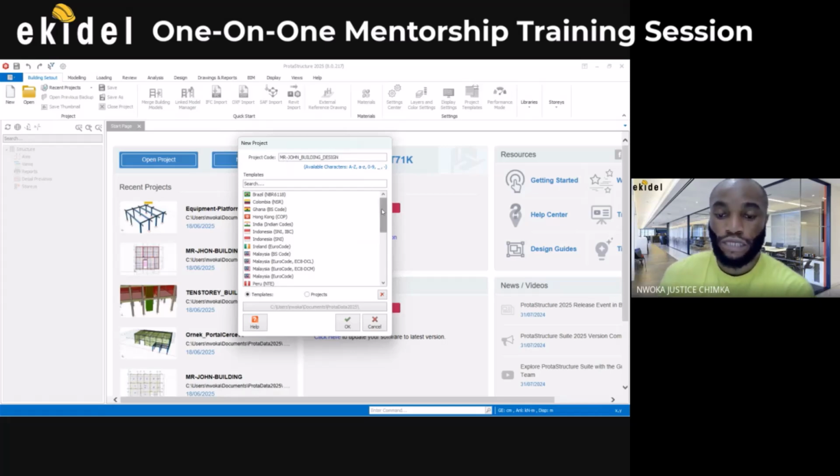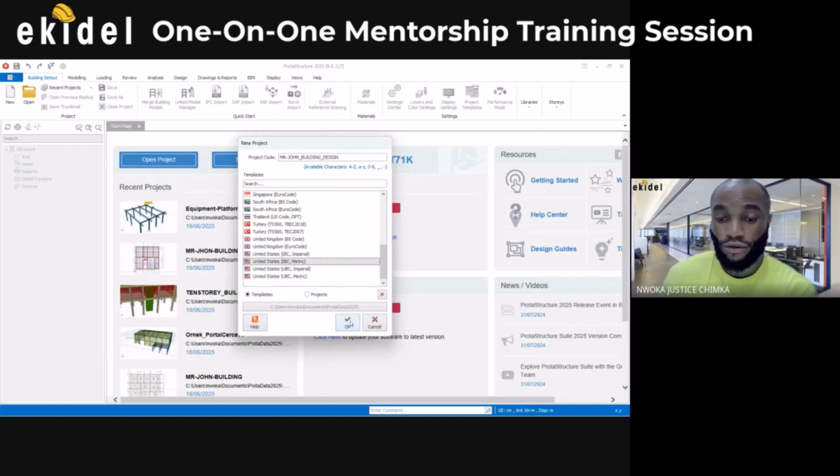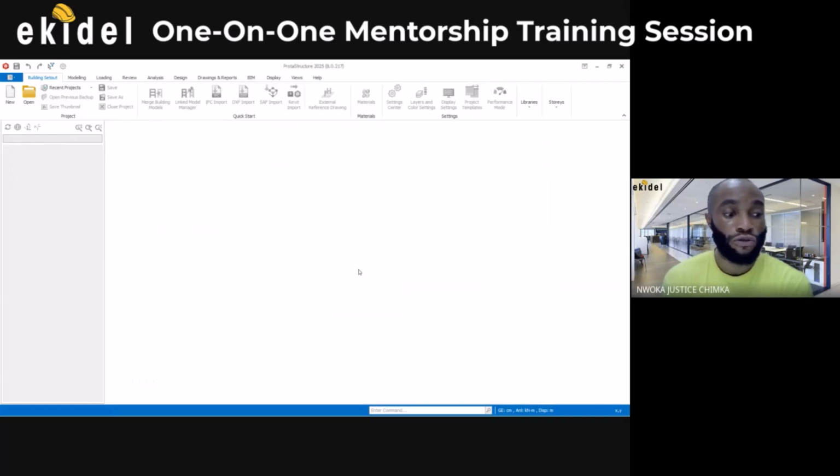So now the next thing to do is to choose your design code. You scroll down here, and then choose your design code. You can see that they have several codes here. So you just come and choose the code that you want. So they have US code, IBC, metric, and imperial. So I'll choose IBC metric. Then with that, I'll say okay. By saying okay, it will import all the code standards into this design environment. So wait for it to load up.